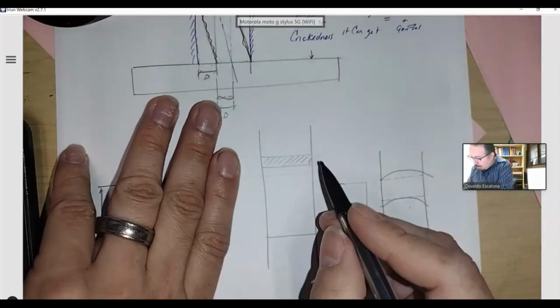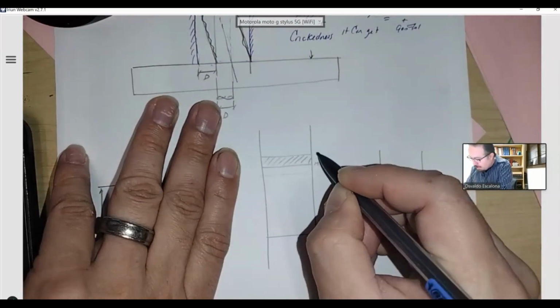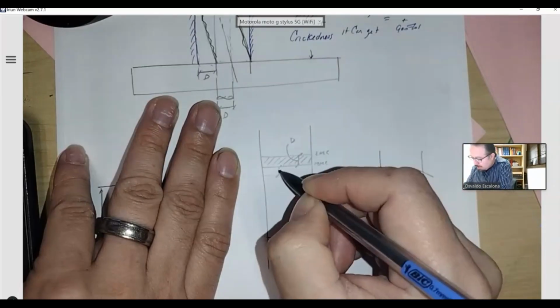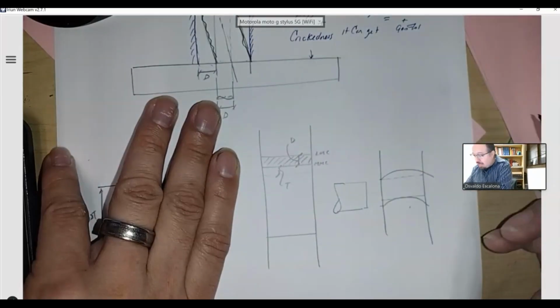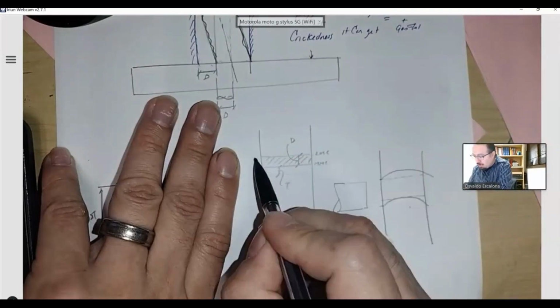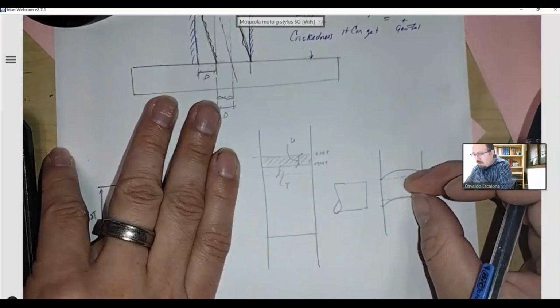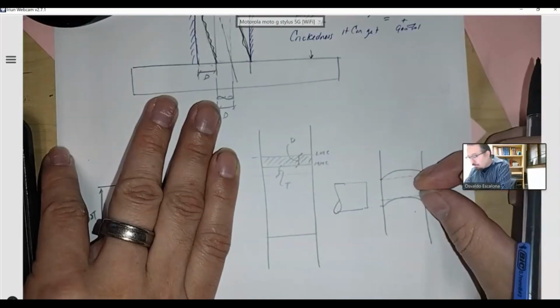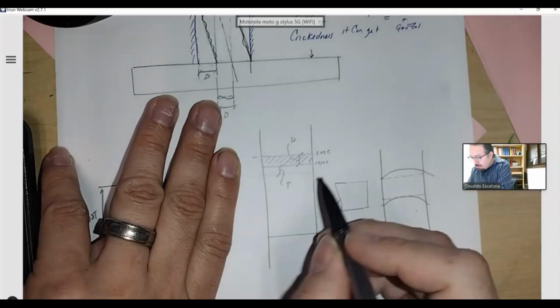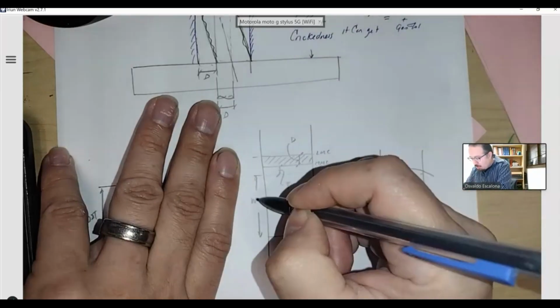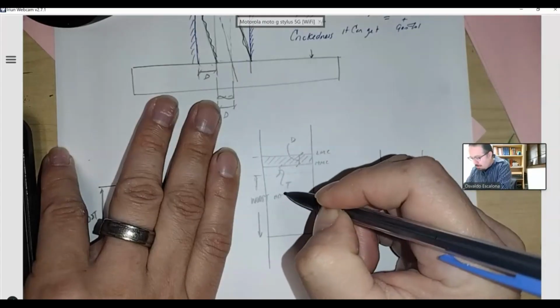So we're still going to have MMC, we're going to have LMC, we're still going to have the D, we're also going to have the T. And this total tolerance that accounts for the hole will live over here. And even after I go and make my hole smaller, let's say this guy will be the worst case condition, because I made it the smallest, worst mating condition.